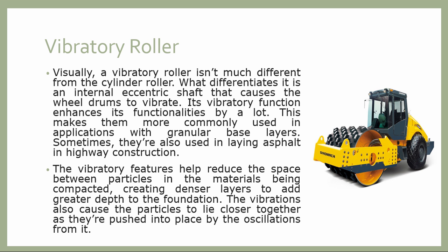Now coming to the next type of roller, that is called the vibratory roller. Visually a vibratory roller is not much different from the cylinder roller, but the difference is that internal eccentric shafts are there, and because of that the wheel drums are vibrated. Its vibratory function enhances its functionality by a lot. That's why this makes them more commonly used in applications with granular base layers.